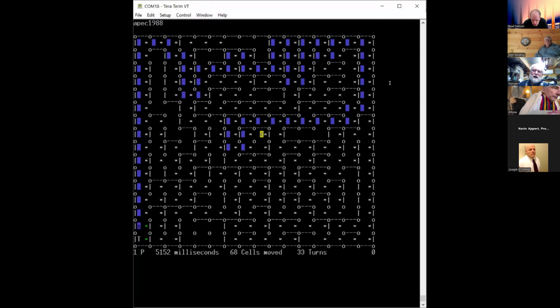And with this method, I would have known how many cells that straight was. So I could do an acceleration profile starting from rest at the start up to peak speed halfway along and then slowing down for the corner. Actually, peak speed would be a bit further than that because I don't have to slow down to rest for the corner, just to the speed at which I can make the corner. So that is the shortest route that this mouse finds. It might not be the fastest route, sadly.